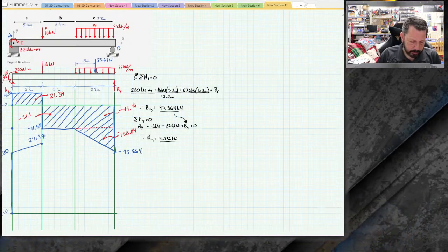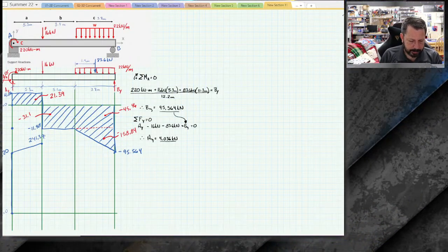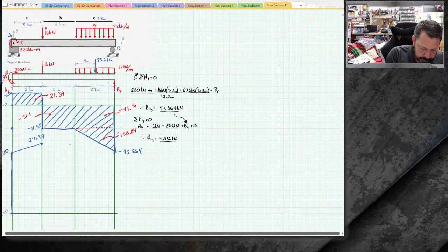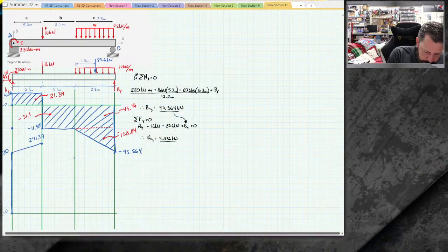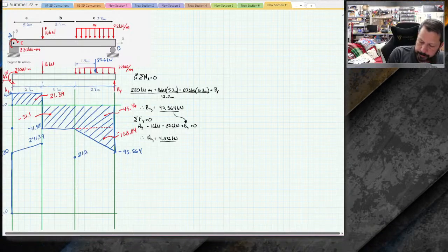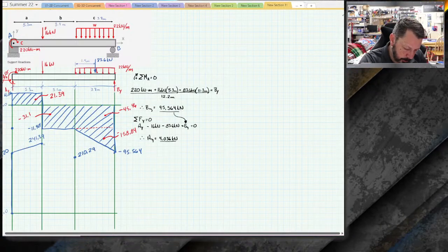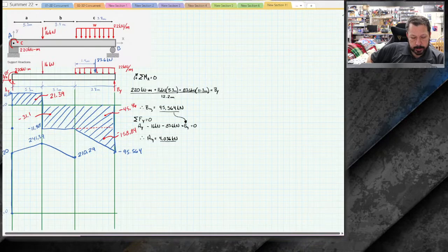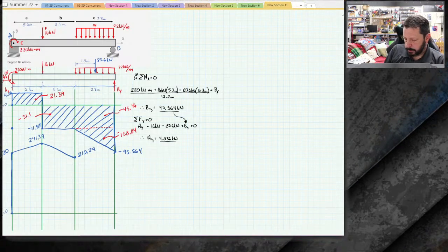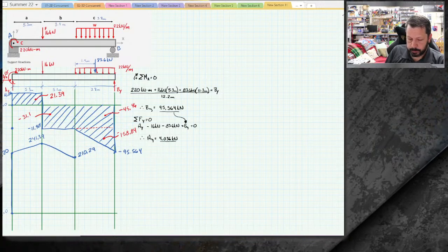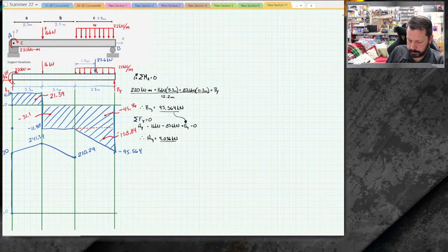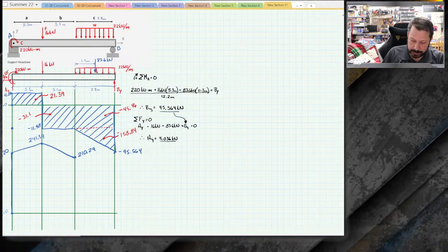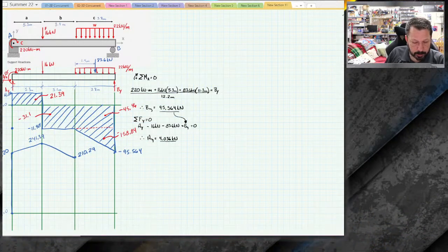Now I start dropping down. So I am at 241.39. The next little section is negative. So minus 31.1 gets me down to 210. We'll say it's somewhere, 210 should be below 220, huh? So there, 210.29. This one's also straight. And then I've got a total of negative 45.46, but I also have to subtract off 158.84, which gets me down to 5.99. So it gets me down to 6. I'm not exactly at 0, but I'm close to 0.